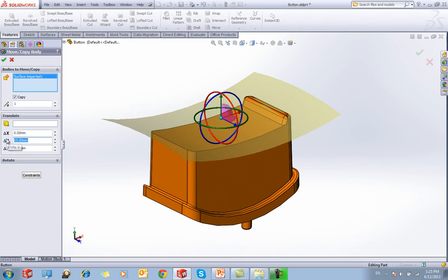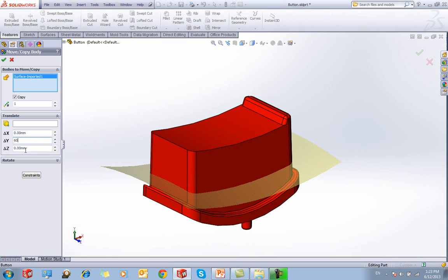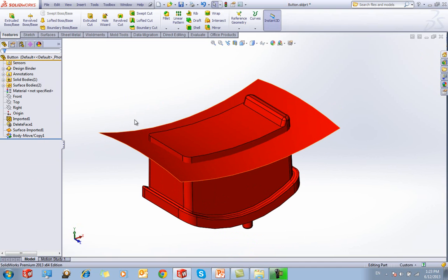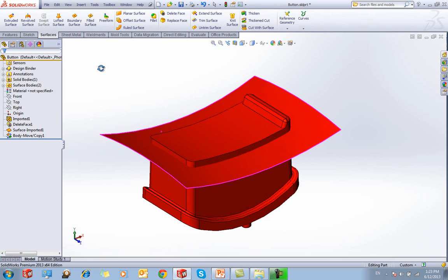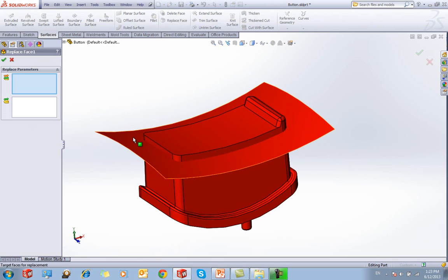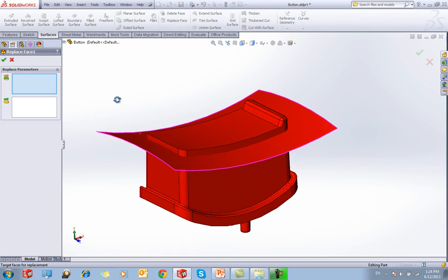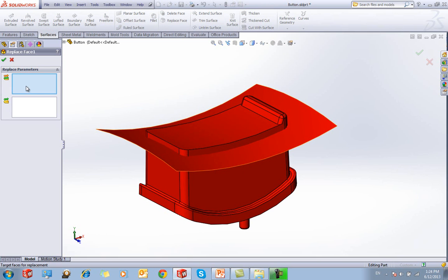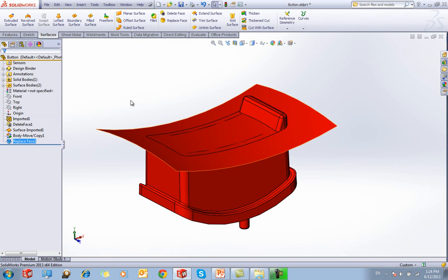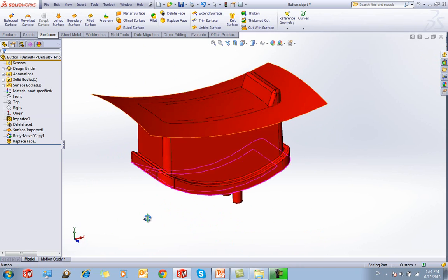Let's say it's 55, 60, 62.5. I'm going to replace this one with this one, meaning this height to this height, following the new shape. I will use the surface function, which we call replace face. I use the surface function here because a surface body is a body. A surface body and a solid body is a multi-body. I always think of a surface as another kind of body. So surface and the new surface. I just click OK. You can see the face is replaced to this.